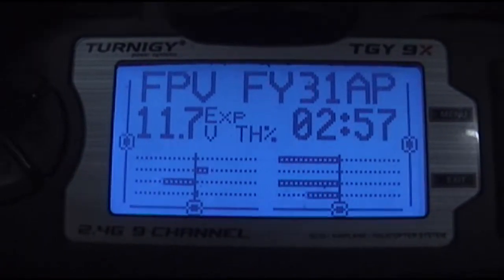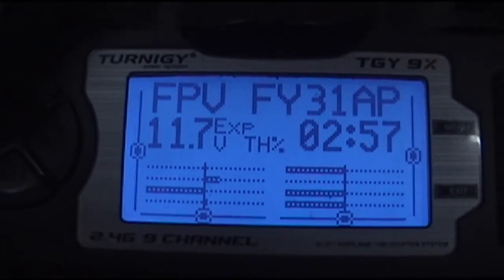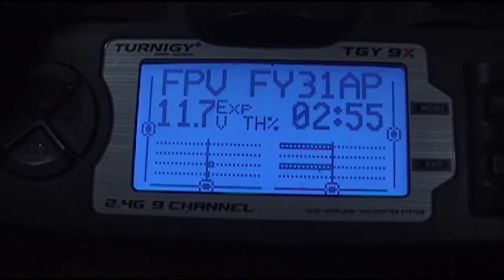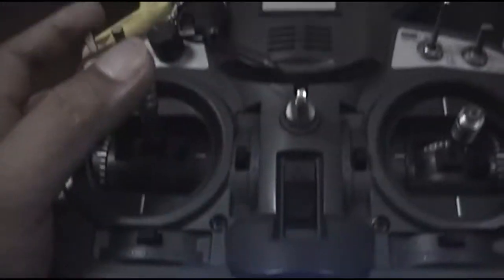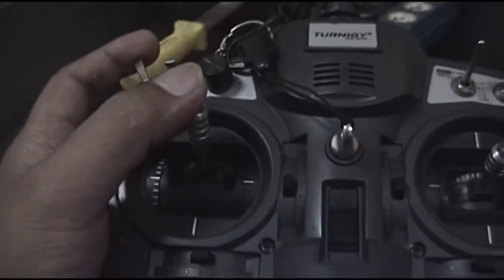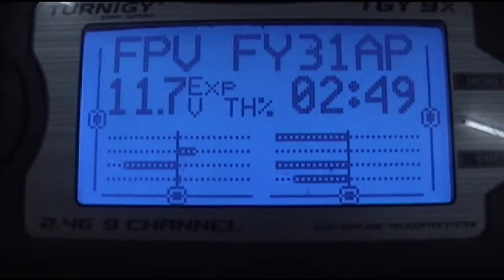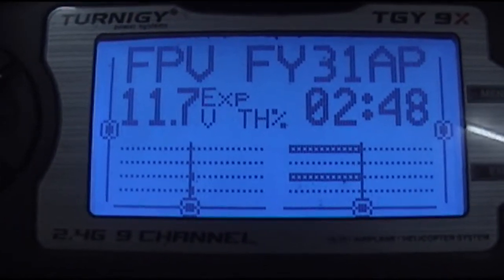And then when you push it again up to mid-stick, the flaps is gone, and going higher above mid-stick, no flaps. And in this mix, I also mix some elevator.